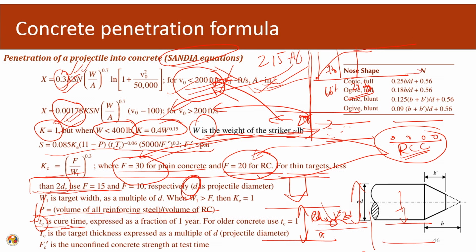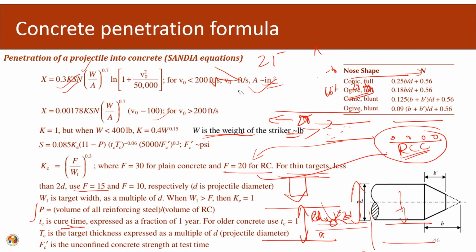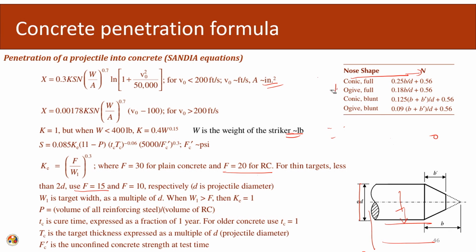In certain types of concrete, like hardened concrete, having very high strength, it will keep on gaining strength across the years, down the line 3 years, 4 years, 5 years. If the target keeps on gaining strength, it will provide more resistance to my impactor. So, the penetration depth will be less for a concrete which has gained more strength.